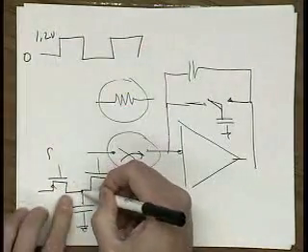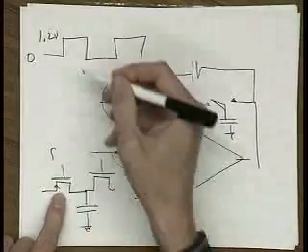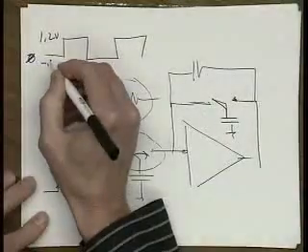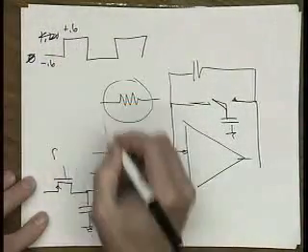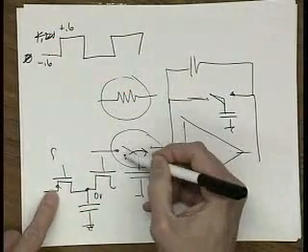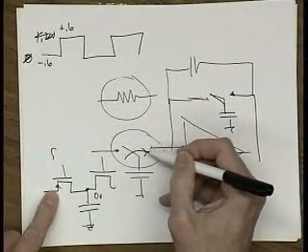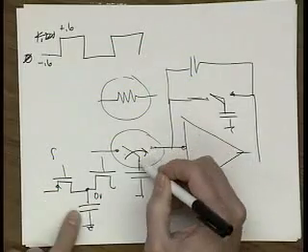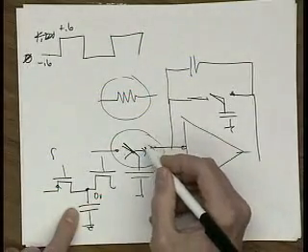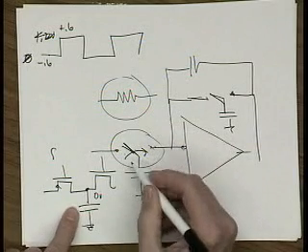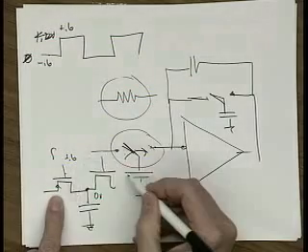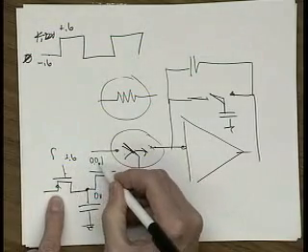So what happens is this transistor slams between being cut off, or let's do it between minus 0.6 and plus 0.6, and let's say this is nominally around 0 volts. So this switch is either shut off or on. This is like a double pole single throw switch. This switch is on when the voltage is high, plus 0.6, and off at minus 0.6.